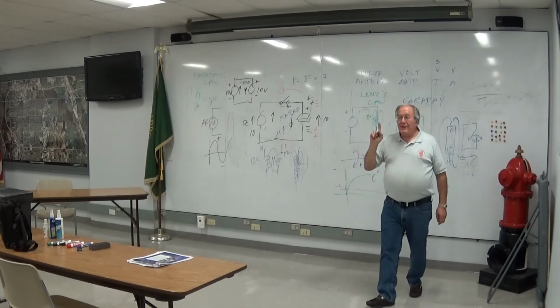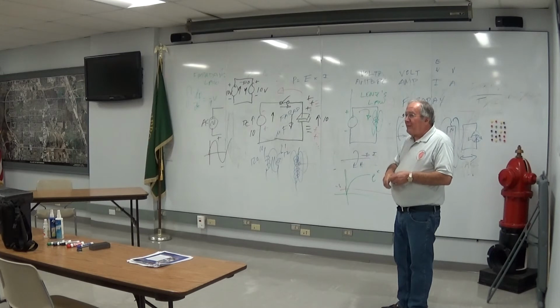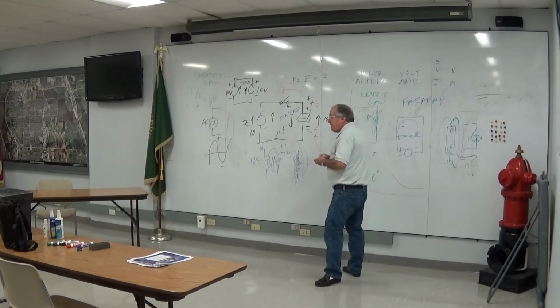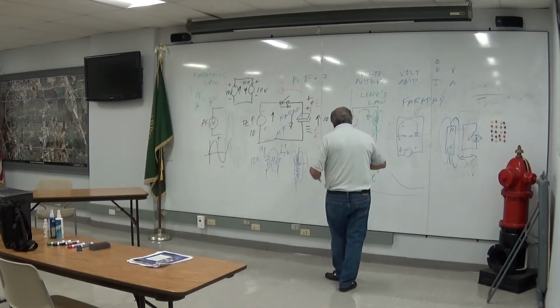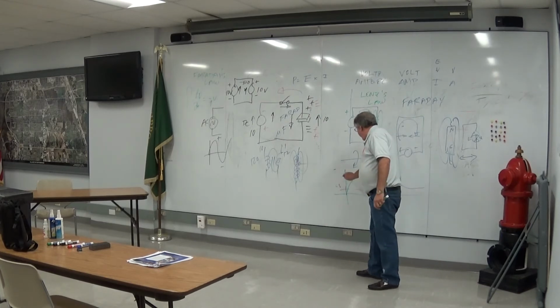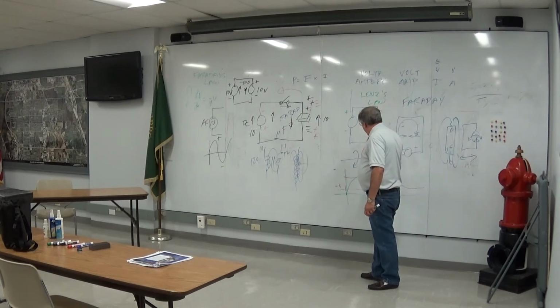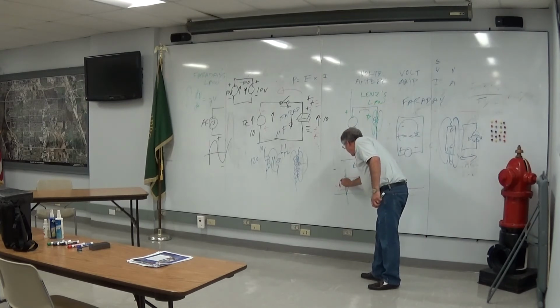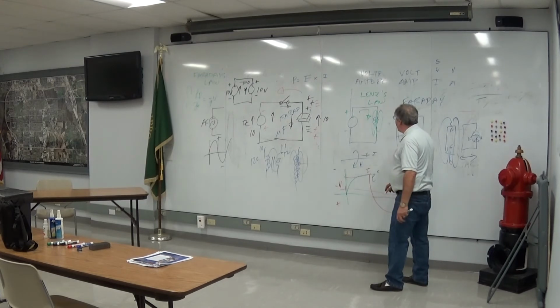It is the reason why there's an impedance when you feed alternating current to an inductor. Because what you're doing with an alternating current, just like you did before, you turn on the juice, and the current this time, not the voltage, but the current builds up to some maximum amount. And when it does, nothing changes. It stays that way unless you reverse the voltage. This was plus before, it now becomes minus, this becomes plus, and then the same thing as before. It goes back to zero and then goes the other direction.